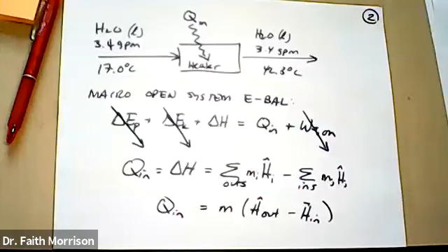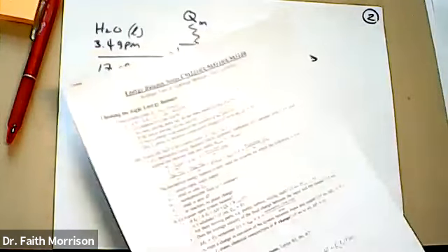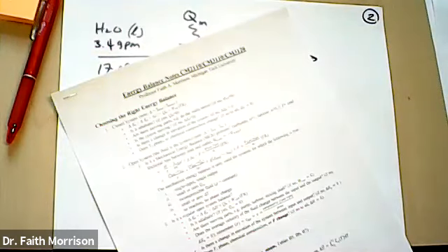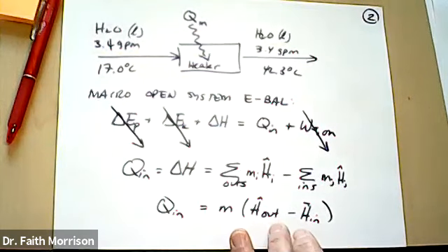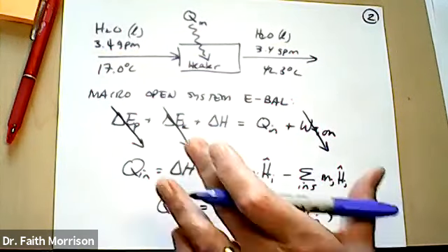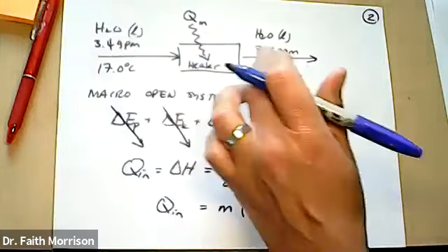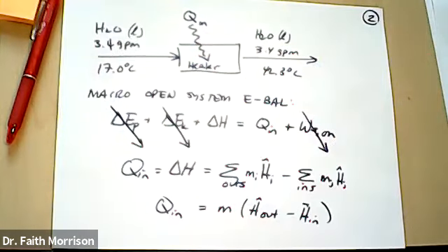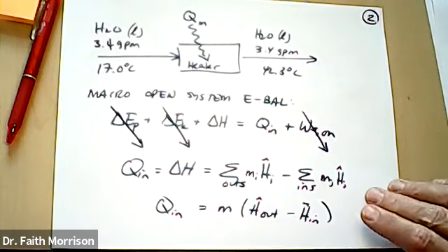Again, if we go back to Felder and Rousseau, which is the book I use, or to whatever text we use to learn our fundamentals of how energy is moved around in a stream, we can find how enthalpy changes are calculated in a liquid when only the temperature is changing. So those are the specifics that we have to keep track of and know to choose the correct step at the next point here.